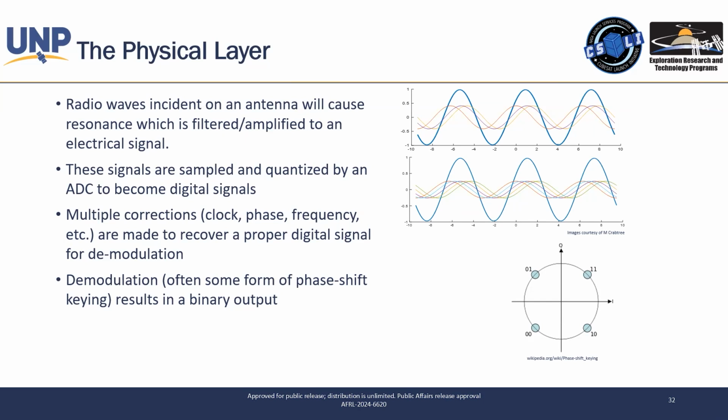So then we can map, in what we call complex phasor space, these signals that are sampled at a certain period of time. And when we sample at a certain period of time, we can see, oh, look, the phase is shifting depending on when I sample them, right? And those phase shifts are what we use to embed our data. Here's a classic mapping of, whenever I see something that's at this phase, I just assume that's a 1-1. The opposite is a 0-0. This is what we call QPSK, or quadrature phase shift keying. It's just a way we embed information into a wave.